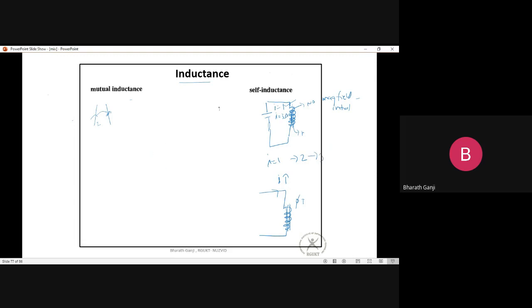Whereas if your circuit was only connected to a resistor, then your current everywhere can instantaneously jump from I equals 0 to I equals 3, if you assume there are no inductive effects anywhere. If there are no time varying magnetic fields, or even if there are, the magnetic field variation is significantly less, then we can assume the current changes instantaneously from 0 to 3. So at any point of time, when you have a scenario like opposition of changing currents, we usually address it with the concept of inductance. In the same way, if you have two circuits, that is self inductance, and of course we saw the definition of mutual inductance also.